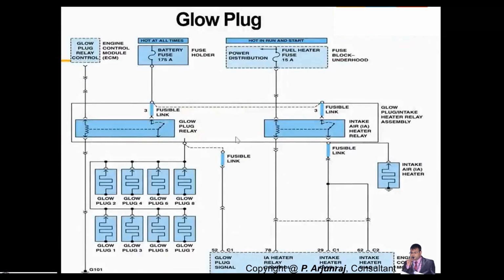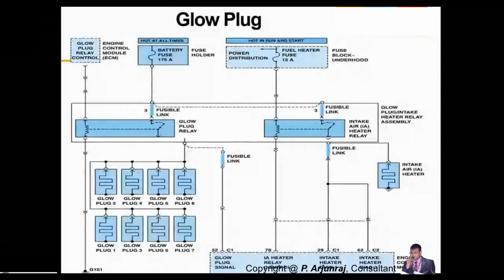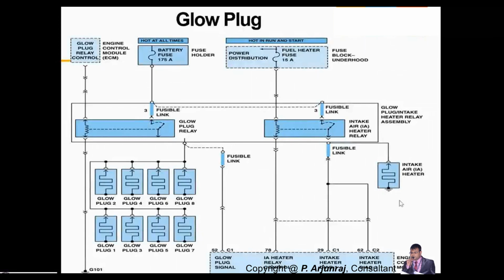This is the typical glow plug line diagram that is used in a diesel engine. It comprises a 12 volt battery system, and it's basically an electronically controlled, computer operated glow plug. It has the relay, it has the battery, and it will preheat and heat the air, and it will give a signal accordingly. It will heat incoming air into the pre-combustion chamber.